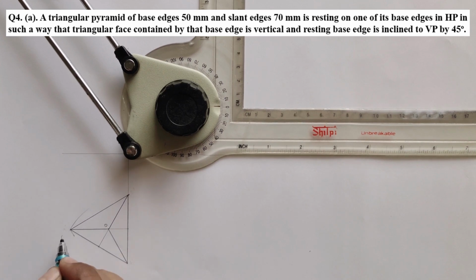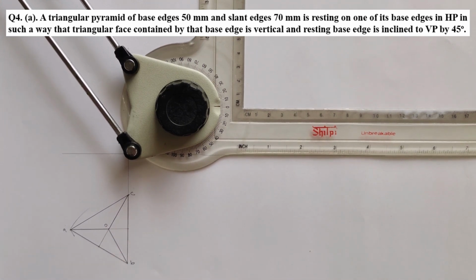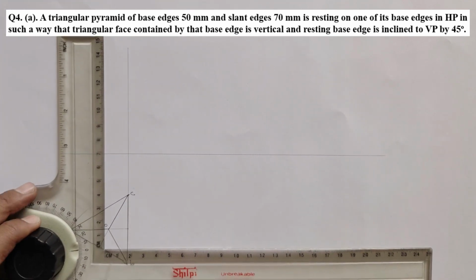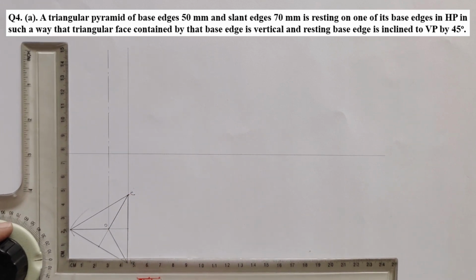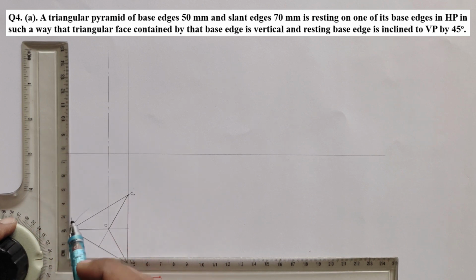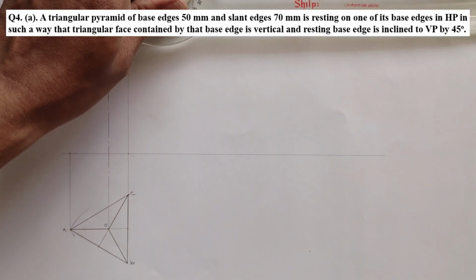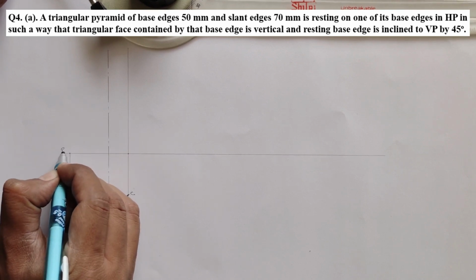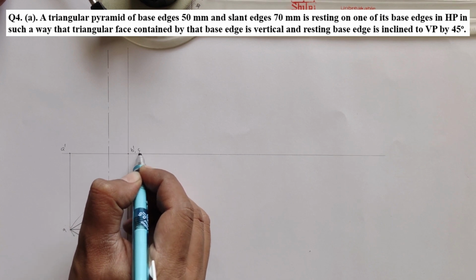So for our convenience, let us label it. I'm giving here A, B and C. This is the resting edge BC, and this is the apex O. Let us take it up. So this will be the axis. Here resting is given on one of the base edge on HP, so neglecting the angle at first, you will have all these 3 base corners on HP. So here it will be the corresponding front view A dash, B dash and C dash.